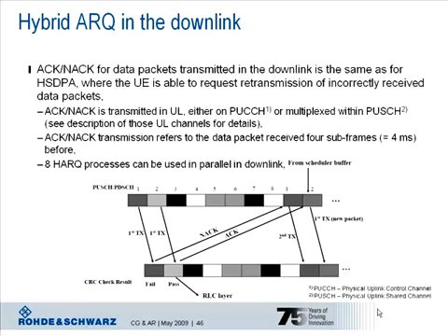In TD-LTE it is a little bit different. Here the timing relation depends on the uplink-downlink configuration, meaning how many subframes are allocated for downlink transmission and how many subframes are allocated for uplink transmission. Because of that, a single ACK/NACK response for providing HARQ feedback could be used in TD-LTE for multiple PDCCH transmissions.